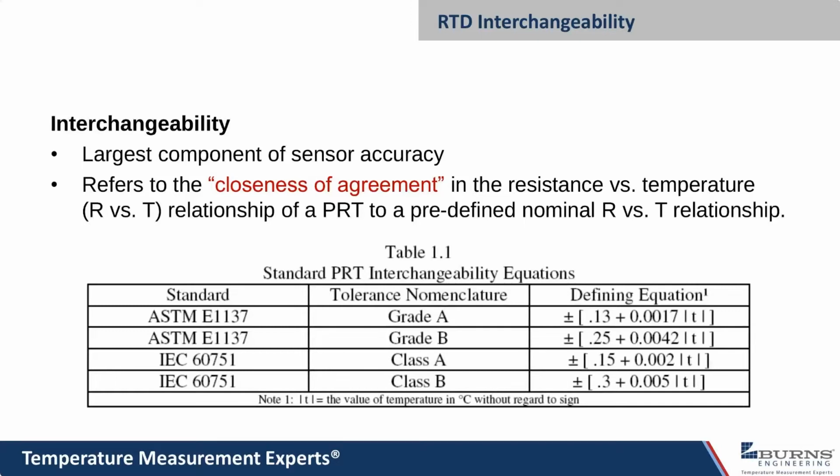You end up with some temperature coefficients, and you can take all that information and mathematically calculate the resistance at a given temperature or vice versa. And both are going to have the same uncertainty of those measurements. So it's not that grade A is any better than a grade B. It was just adjusted a little bit tighter at 0 degrees C when it was made. Hope that answers that question.